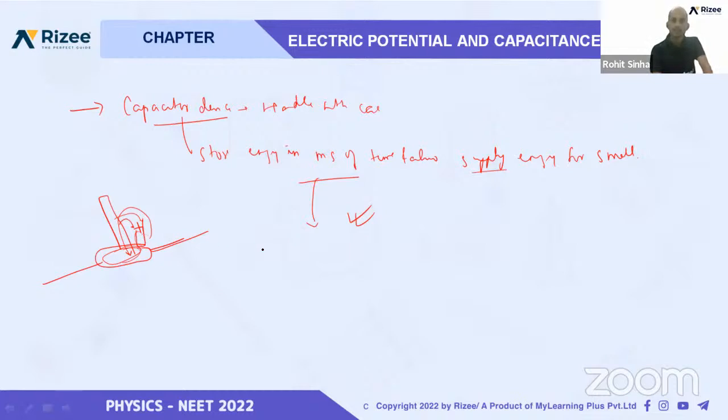Okay. Sometimes it is said that a capacitor may have some charge. So if we are trying to touch the fan or any device containing a capacitor, first we should discharge the capacitor. You must have seen electricians touch both wires and discharge the capacitor, and then they do other things.